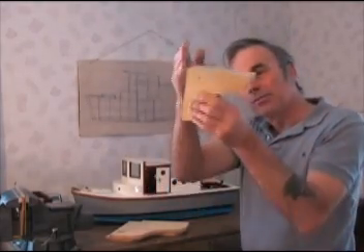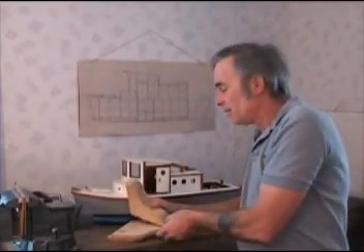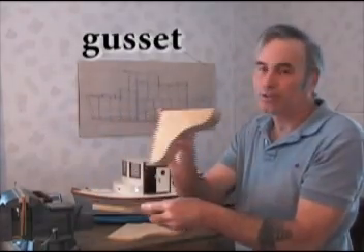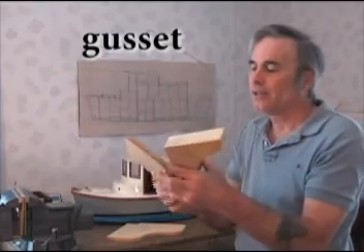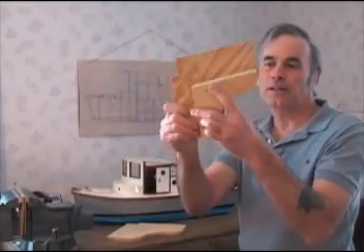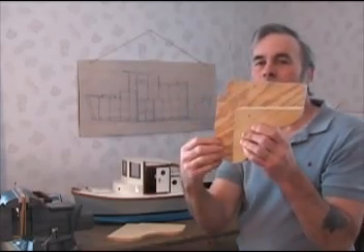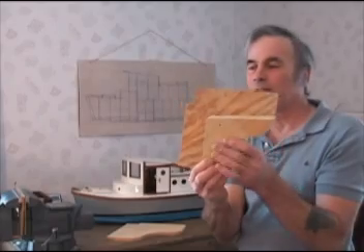Now this goes between the cabin side piece and the deck beam. What makes it a gusseted knee is that these plywood pieces are called gussets. This is the width of the two framing pieces I'm tying together, and this goes on either side to sandwich the two framing pieces and this knee block here.